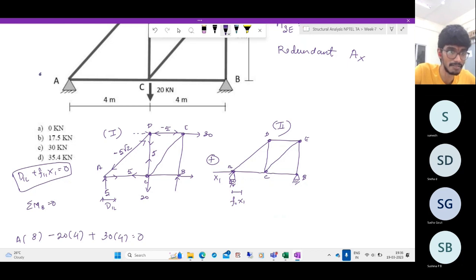So that is very simple. You just consider this joint. There is 5 root 2 acting here, and you have some unknown forces in these two directions. So the resultant has to pass through this. So this has to be a downward force and this has to be a leftward force. So this is 5 and this is 5. Simple.